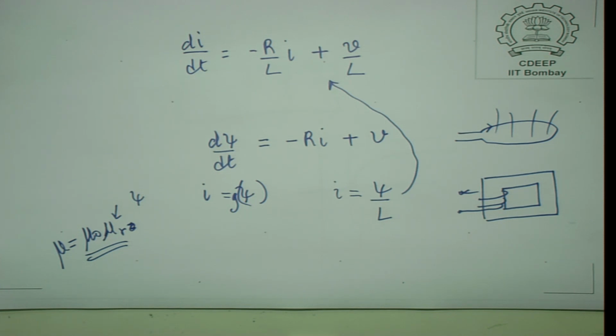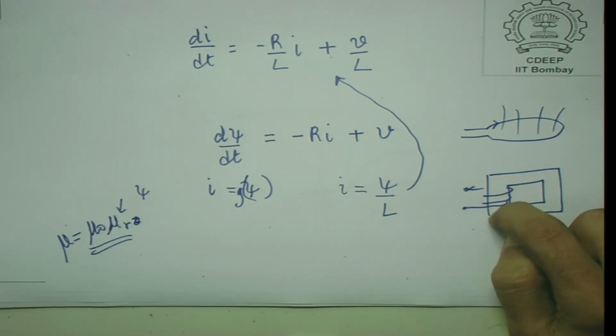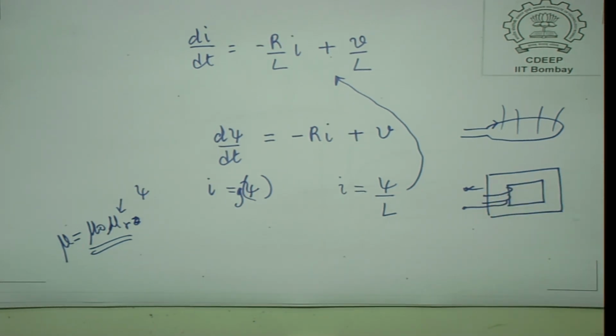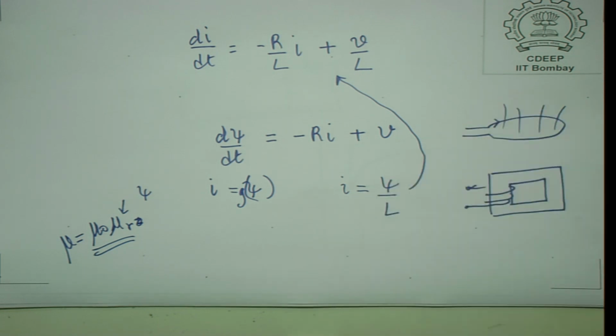Now, what I mentioned some time back was normally we use a ferromagnetic core, and because the ferromagnetic core has got a relative permeability, for a given external current through this winding, the flux in the core is usually much more than what you would expect in free space, because this ferromagnetic material itself has got atomic magnets, you can say, which get aligned and enhance the flux in the core.